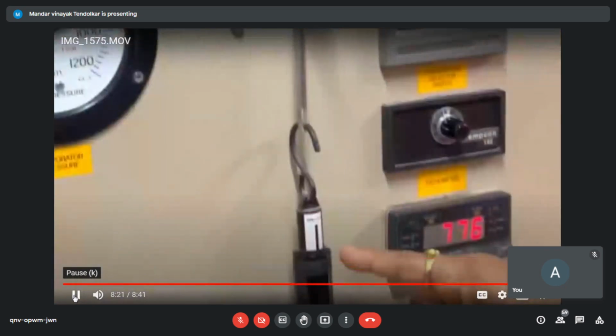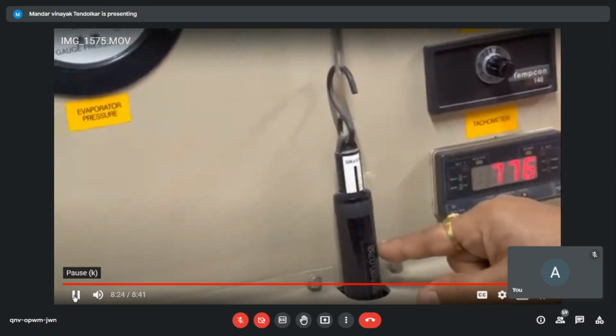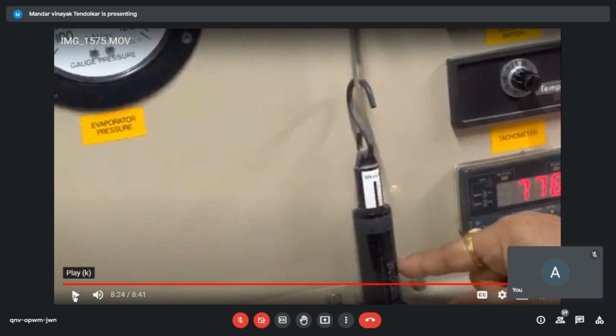And next part. This is the spring balance, which is calibrated in terms of newtons directly. So you use it directly because the length of the dynamometer arm is known to me. So directly calibrated in terms of Newton, that is force. Force into displacement, you get the work, or basically work per unit time, that is the power, the compressor power in watts or kilowatts, whatever it is.